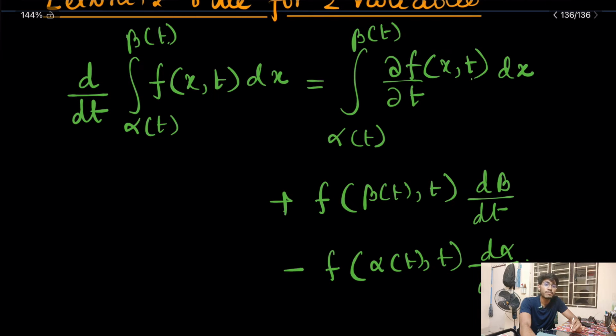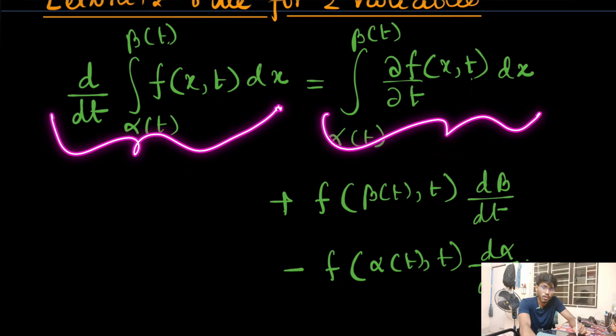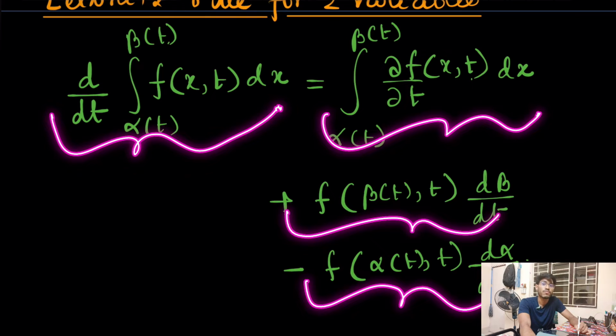Now in fluid mechanics we have a very important theorem called Reynolds transport theorem. If you have already studied that RTT, then you can correlate that this is the total change of any variable that can be conserved. This is the change in the control volume, this is the outgoing flux, this is the incoming flux.